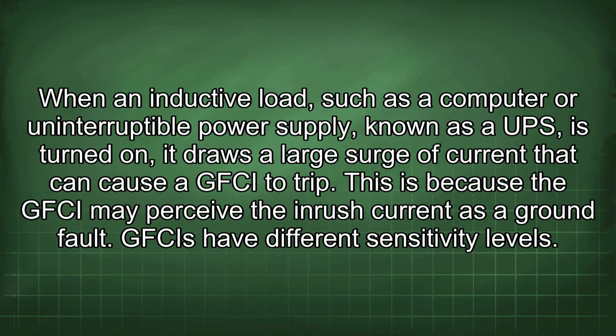When an inductive load, such as a computer or uninterruptible power supply, known as a UPS, is turned on, it draws a large surge of current that can cause the GFCI to trip. This is because the GFCI may perceive the inrush current as a ground fault.